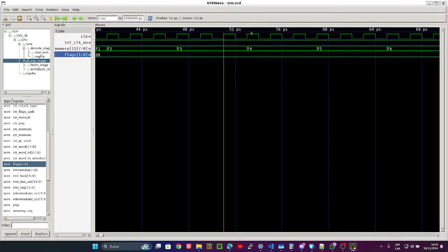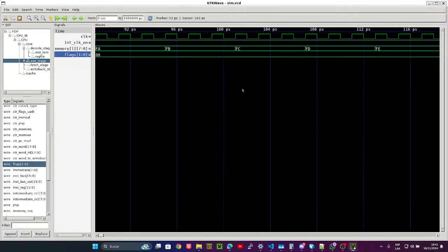But that PLL needs to essentially stabilize when you start the FPGA. It has a clock output for the slower clock, and another output for the locked signal, which tells you it's accurately giving the frequency you asked for. I just took the locked output and ANDed it with the clock. Okay, it did work, but don't do it. At least it worked. I was running it at like 10 hertz.